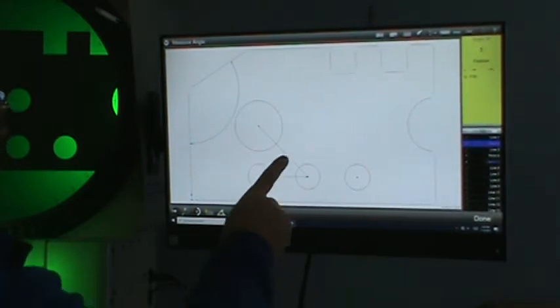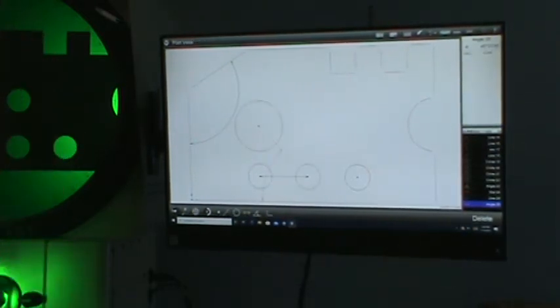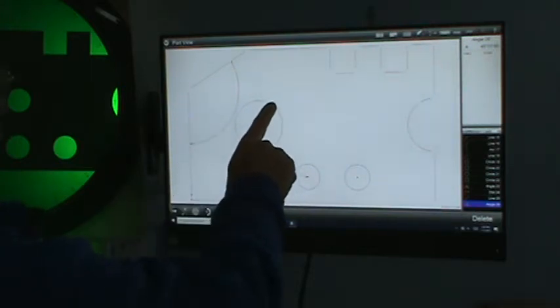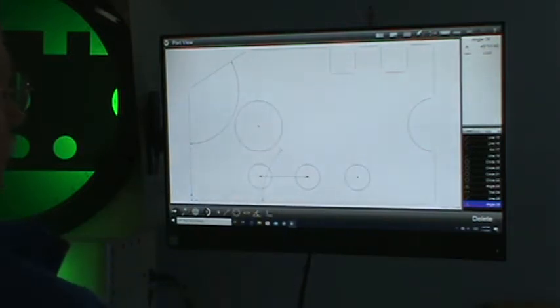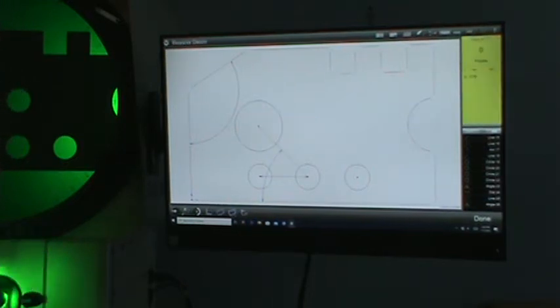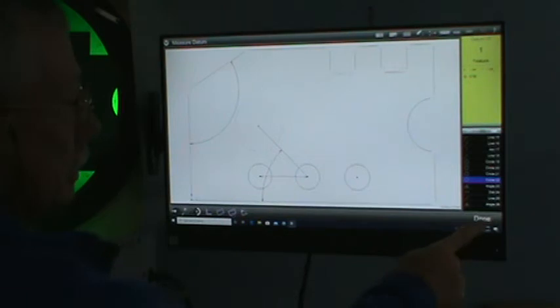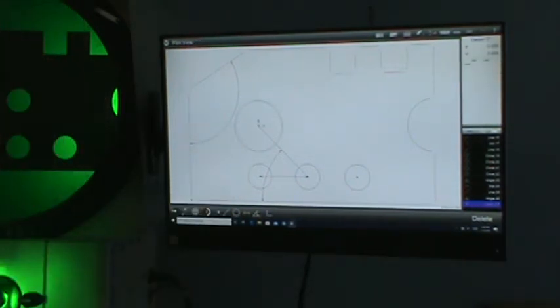I want to use that line, and I want to use that line. Boom. It says it's 45 degrees, 1 minute, 40 seconds. Okay? Let's say, for instance, this hole becomes 0. You say you want to set an origin here. So what you do is you hit the alignment. You say, okay, I want to set origin. It says, where do you want to set origin at? I want to set it on that circle. And then you say done. So now that's your datum.